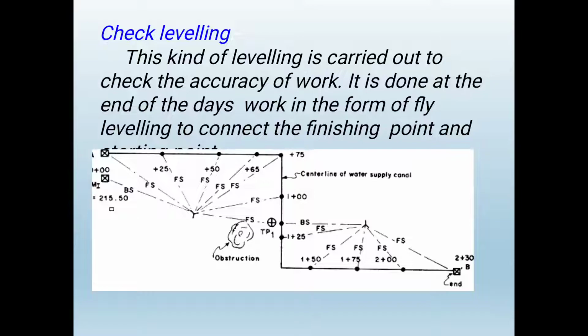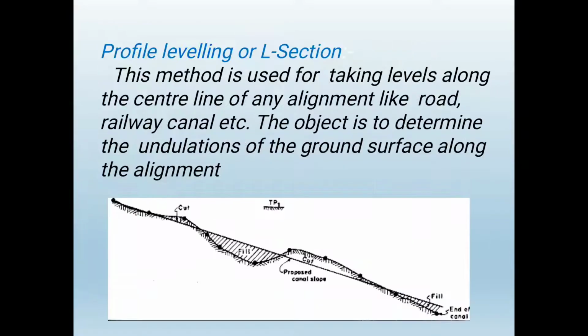Check leveling. The fly leveling done at the end of the day's work to connect the finishing point with the starting point on that particular day is known as check leveling. It is undertaken in order to check the accuracy of the day's work.